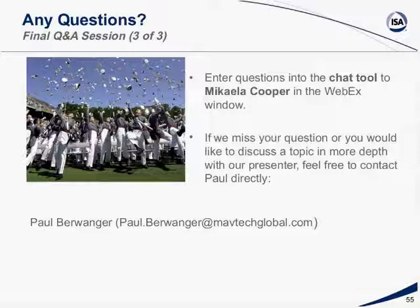Next question. How do you distinguish if an alert overlaps an alarm? That's done during the rationalization process. You take a look at the different points. If you take a look at what happens with each tag, and you have an alert and an alarm on the same point, you basically don't need both. It can be an alert or it can be an alarm, but it's not both, and you do that during the rationalization process. A lot of times it'll come up.